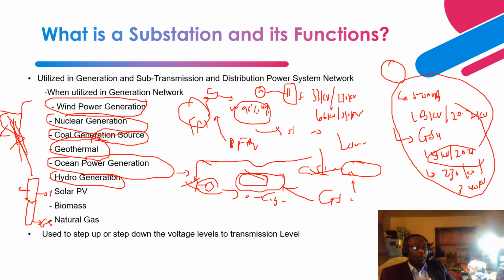The water that flows through the penstock from this dam flows at very high energy, and there is a lot of potential energy from this height. As the water impinges on the vertical mounted turbine blades, it starts rotating them. Because the turbine is coupled through a coupling to the shaft of the generator, the rotor automatically starts rotating.